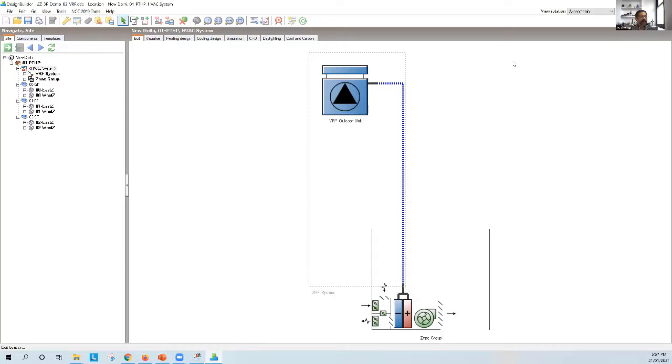Some of the newer Daikin systems, yes, they do give you small capacity systems with inverter compressors, and they can be quite efficient. Some of the things to watch out for is that you look at the condenser specifications, there will be a cutout temperature. So, it'll tell you that if the ambient temperature goes above a certain point, then actually the system cannot produce any useful cooling, and the compressor might shut down.